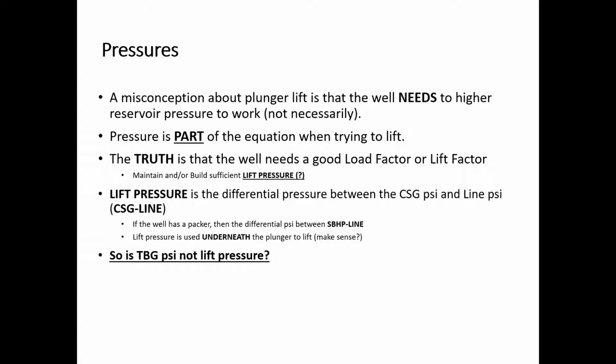Notice I said lift pressure. Lift pressure is the difference between your casing pressure and your sales line pressure. If a well has a packer, then it's the difference between your reservoir bottom hole pressure differential and your line pressure. Lift pressure is often thought of as tubing pressure, but your lift pressure is underneath the plunger.